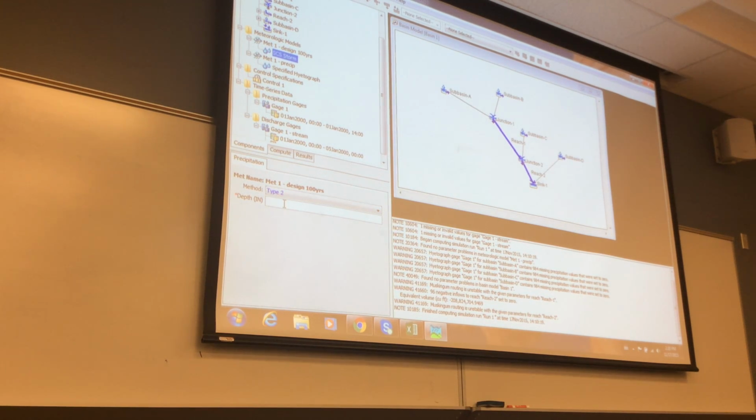And we would go into the IDF curve, given duration, calculate a given depth in inches. So I'm going to go with 9.2 inches. Don't do your project with 9.2. I'm just randomly saying 9.2. You're going to go here and get the right number. Do you all hear me?